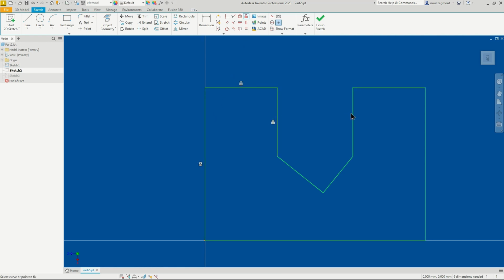The problem with constraining certain lines is that unwanted lines can also change, and to prevent that, we have got to use the fix function, which will lock lines into place so as to prevent them from changing shape. We also want the angle to be in the very middle of the shape itself. To do that, just make the lines equal, and that's it.